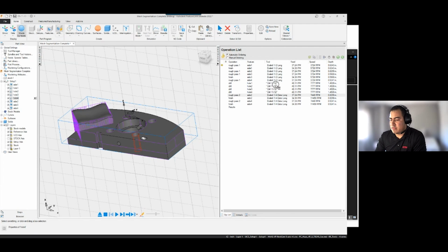So the first thing that I want you to take a look at is that by selecting the actual property of the toolpath, we're able to modify that toolpath and say, instead of using a drill that you couldn't find for a specific size, go ahead and just use the drill that we just selected, right? And it applies that and takes care of the error messages for us. Now, again, that was a very manual process. What I can do is actually select a handful of features or a handful of toolpaths and apply a specific tool to those toolpaths. So take, for instance, we have a couple roughing passes here. You have a finishing pass for the sides, it looks like.